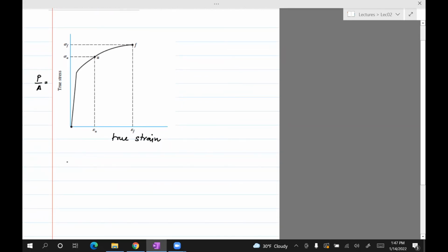The definition of strain is the change in length divided by L. When we wrote down the strain, we just wrote delta L as L minus L0, but a better way to compute the strain is to treat this as dL, a small element. Then, if you remember calculus, to find the strain you just integrate that from the length L0 at which it starts to the new length L.